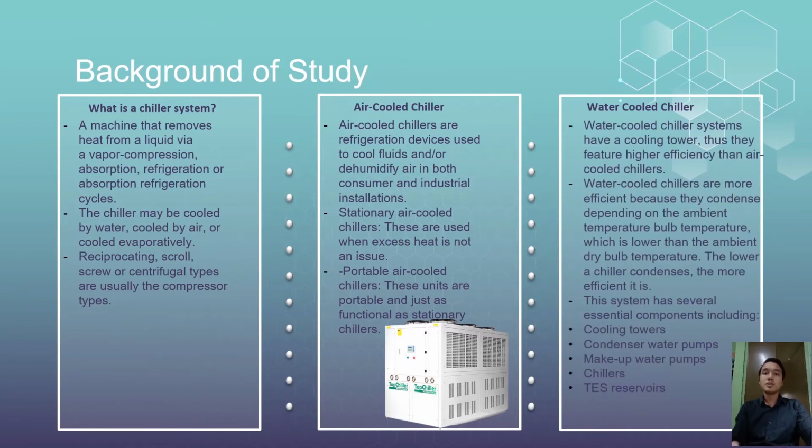Thus, they feature higher efficiency than air-cooled chillers. Water-cooled systems are more efficient because they condense depending on the ambient wet bulb temperature, which is lower than the ambient dry bulb temperature. The lower a chiller condenses, the more efficient it is.